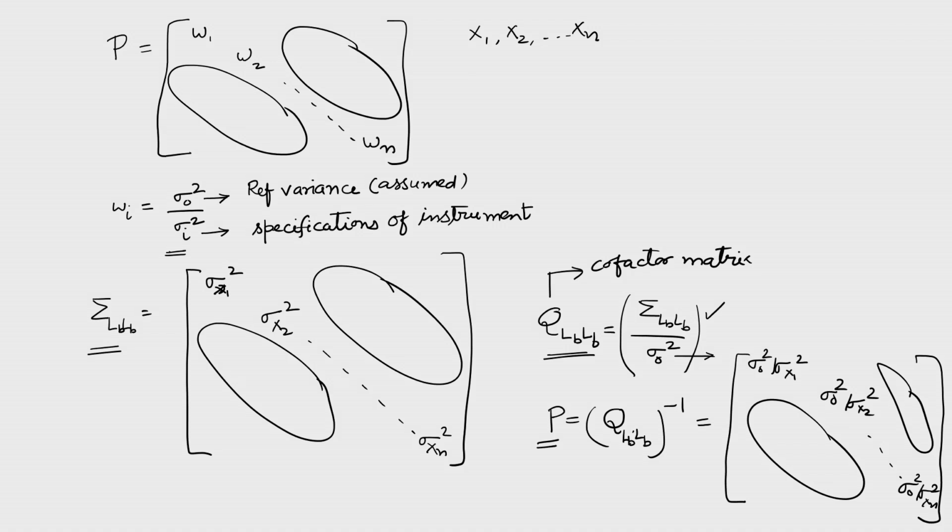Now, here if you see carefully, by taking this ratio, I have eliminated two problems. The first problem, which was the minor problem, was the numerical error. That means, if I take the observations in centimeter or meter, then the value of this sigma will be in different units. And as a result, if I take this ratio, it will remove the factor of units. And so, even if someone takes centimeter or someone takes meters, it does not matter.